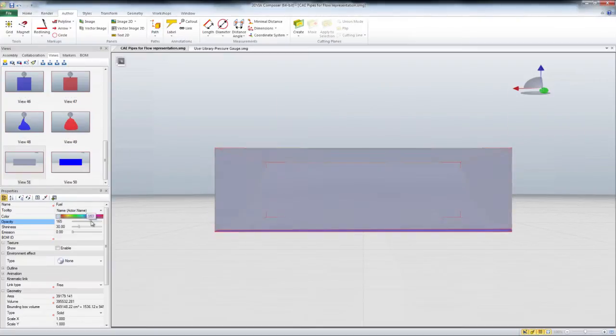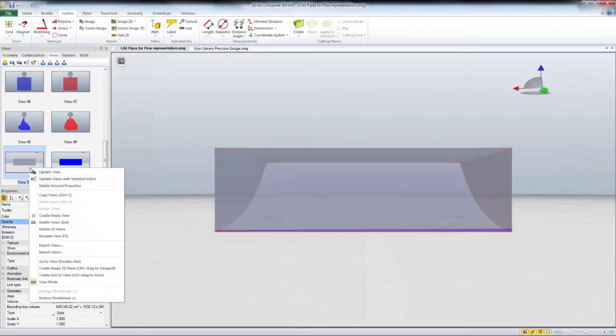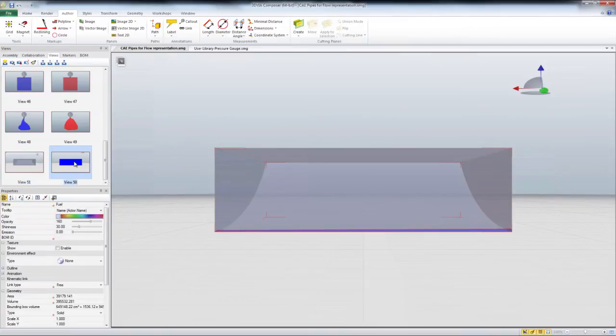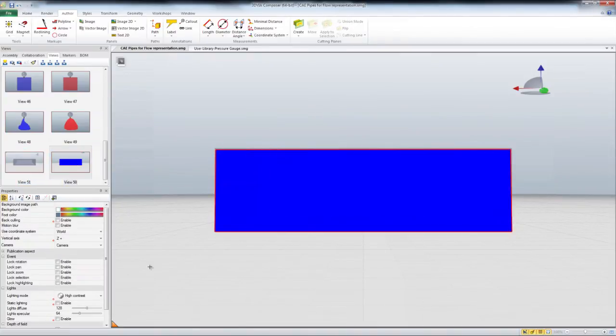Now for the final, having gas tanks filling up, I just drew a primitive polyline on view 1 and changed the shape on view 2, and again animating between the two. You could use a geometry primitive here if you wanted to and map a texture on and get fancy, and you can refer back to the animating flow podcast that I did earlier, but very simple, easy ways to quickly get the information across. Hope these little tricks help.